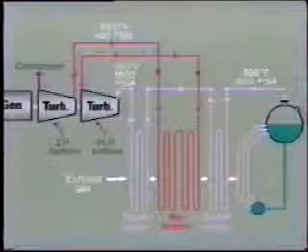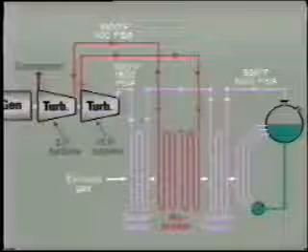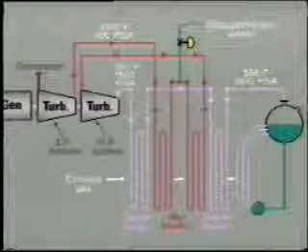It consists of a bank of tubes, and these are located in the same zone as the superheater, so as to produce a hot reheat temperature of, say, 1,000 degrees Fahrenheit or 540 degrees Celsius, the same as the main superheater temperature. The reheater may be split into primary and secondary banks with a de-superheater located between them to permit control of hot reheat temperature.